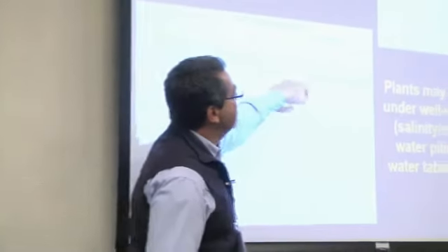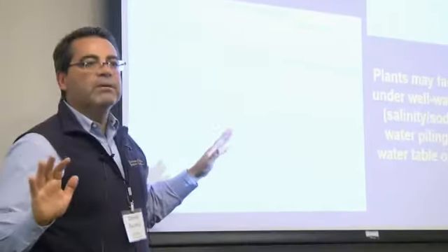That happens because of salinity, sodicity, so you cannot spot this problem easily with soil moisture. But look here. There's a saline soil, and it shows that the soil moisture is pretty good. No problem. But the plants were feeling a lot of stress. The stem water potential was showing the stress. The soil was not showing any problem.